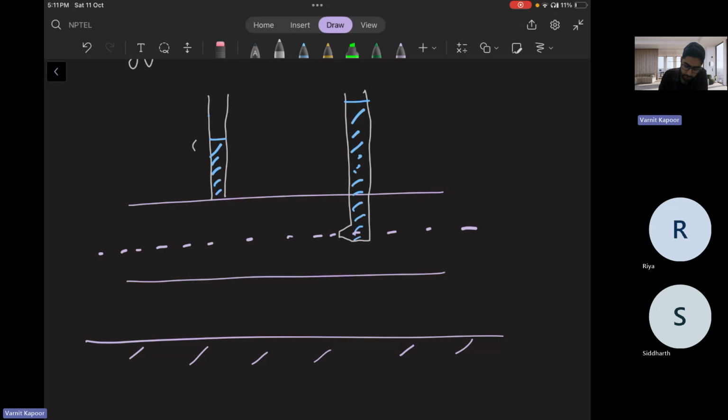So it should be a static head. So this will be P by W. Till this position we have Z from the center line. This is also static. Pressure here is P, whereas pressure inside is P naught, let us suppose, because sudden stoppage has happened because of the presence of the obstruction. So this total head is nothing but P naught by W, that is the stagnation head,